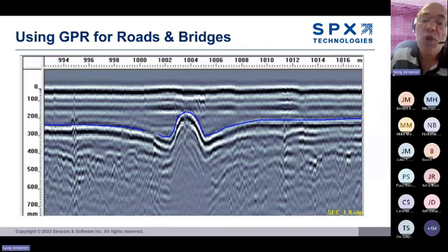So roads are supposed to be consistent and uniform. Consistent asphalt thickness, consistent base course thickness. They often core roads to confirm this, but they often core randomly or at equal intervals. What GPR is really good at, especially in enormous data sets like what you get when scanning roads, is it shows anomalous areas. That is, locations that are different than everywhere else. The places that break up the consistency I talked about.